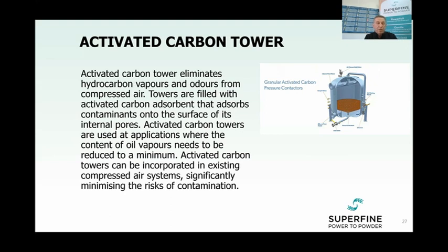Towers are filled with activated carbon adsorbent that adsorbs contaminants onto the surface and internal pores. Activated carbon towers are used in applications where the content of vapor needs to be reduced to a minimum. Activated carbon towers can be incorporated in an existing compressed air system, significantly minimizing the risk of contamination.